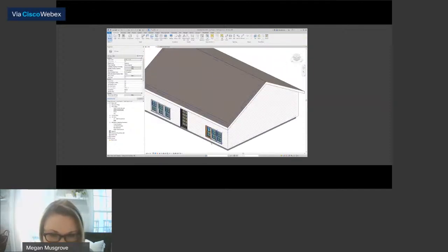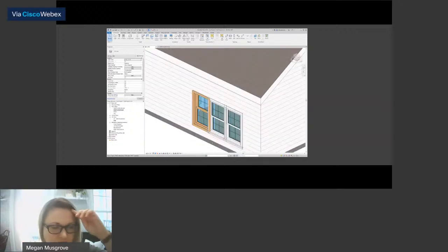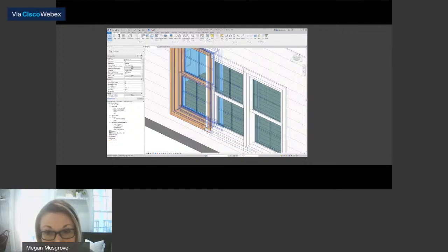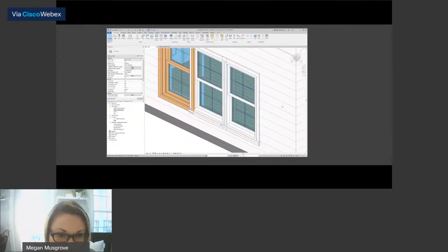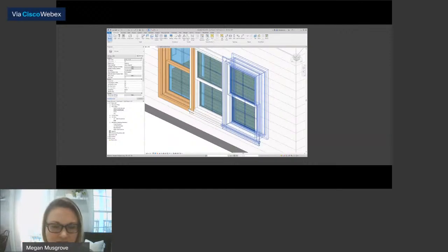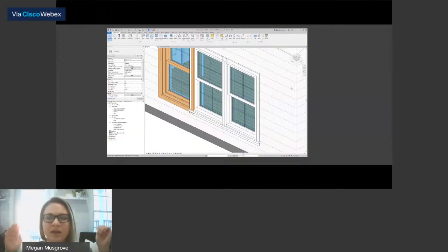So, remember I said they were kind of going different directions? Well, this is really showing that because this is a different material on the inside and the outside. Windows, in case you don't know this, or if you're in a different part of the country where double hung windows or single hung windows aren't common, when you have windows double hung, single hung with 2 sashes like this, the top sash always sits to the outside. So you think of it like if rain is running off of them, if it went the other way, then it would catch water. And obviously we want things making up the exterior of our home to shed water.